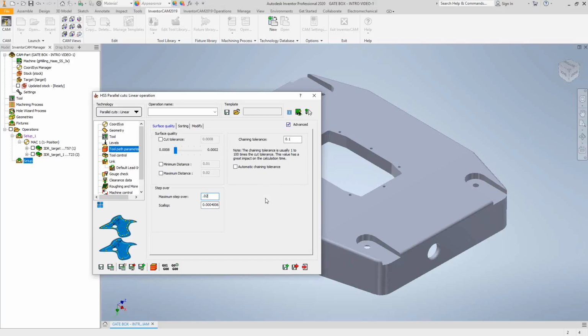Everything on the top half here is to deal with the fact that sometimes you're dealing with a translated surface, maybe something from a customer's part file, an IGES file, step file, and that sort of thing. So all these tolerances on the top half are really just to fine-tune the toolpath so you reduce data points, so you're not driven by the surface completely, because it might be a bad surface. There might be some erratic data in those surface points. So you might want to either fine tune it or make it a little coarser, so you don't actually have to deal with a bad surface that is in the design side and then machine that.